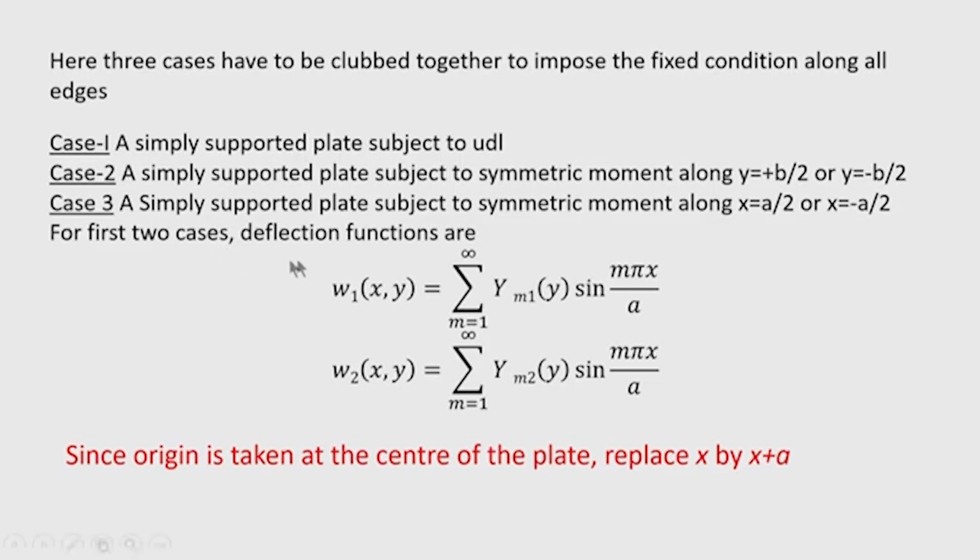For the first two cases, deflection functions are given, because these two cases require that the plate is symmetrical about the x axis. Okay. So, that we have got, but the origin is taken of course at the center of the plate, and therefore, x has to be replaced here by x plus a. So, that should be noted very carefully, that x has to be replaced by x plus a.